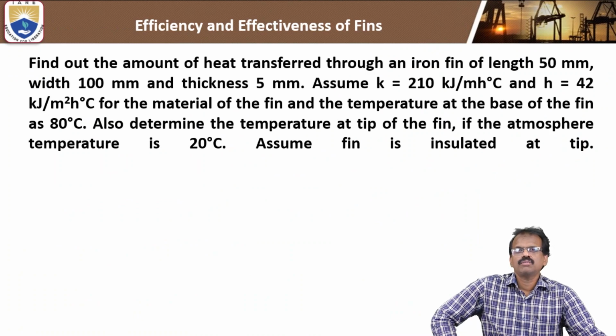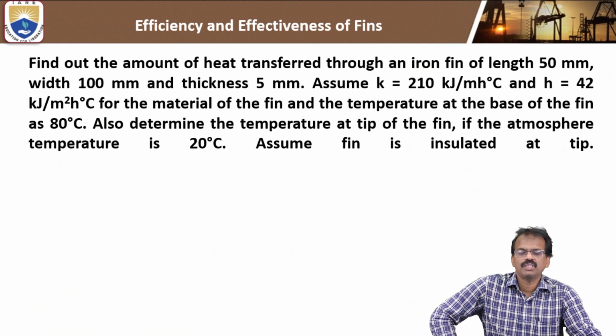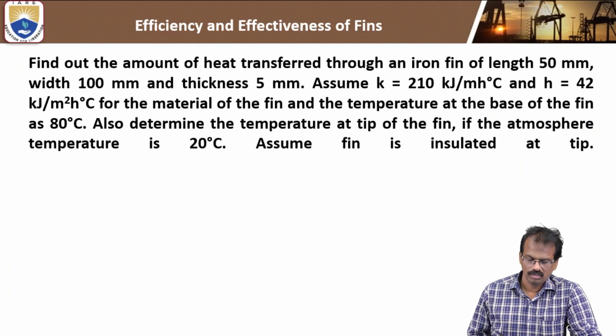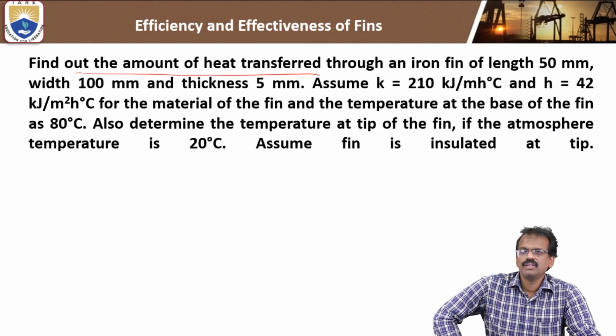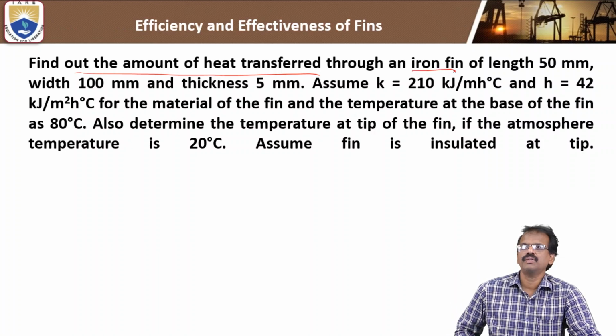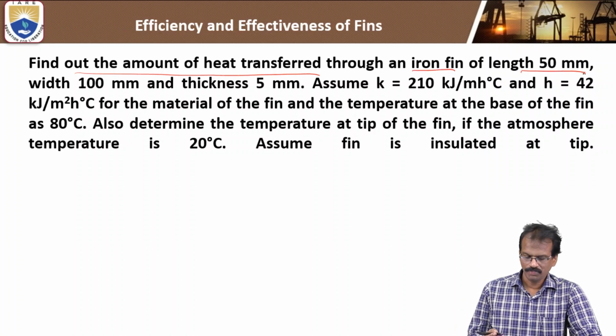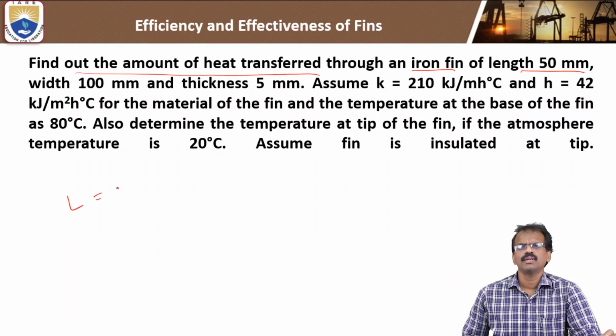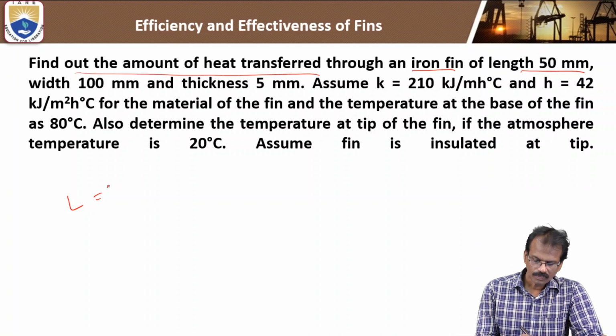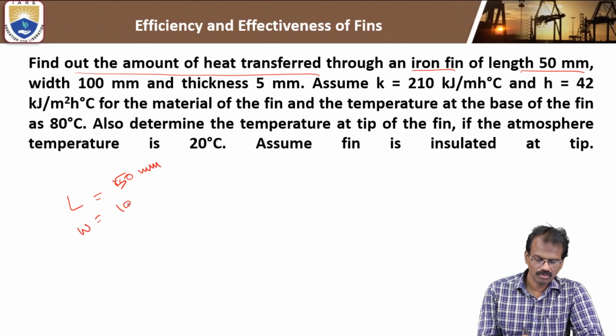Okay, so we'll solve one numerical based upon the fin, then we will conclude this class. Find out the amount of heat transferred through an iron fin. The material of the fin is iron. The iron fin length is L equal to 50 mm, and width is equal to 100 mm.